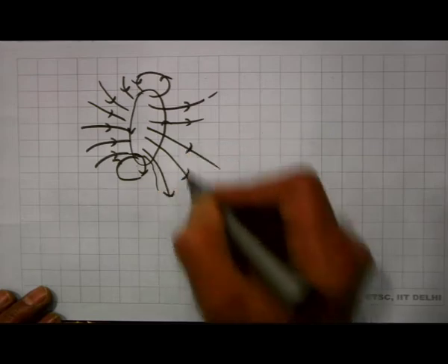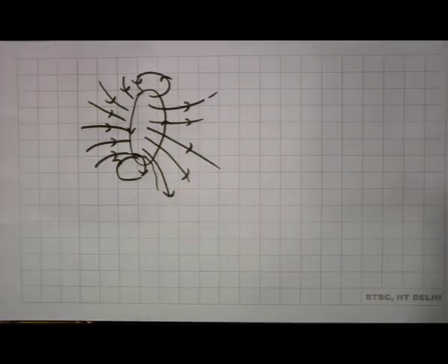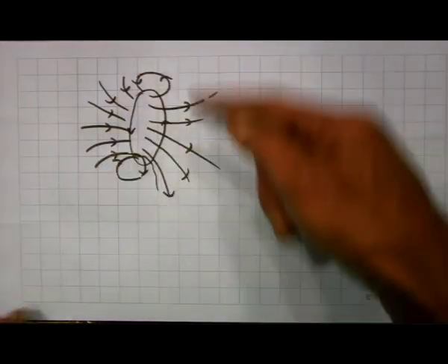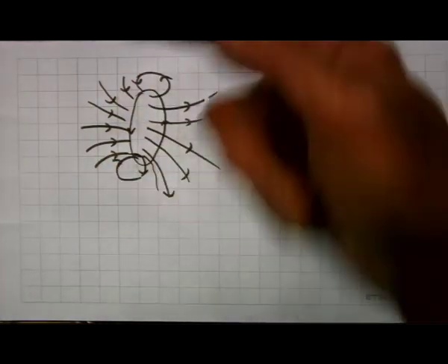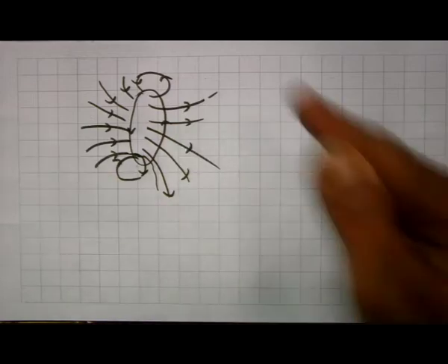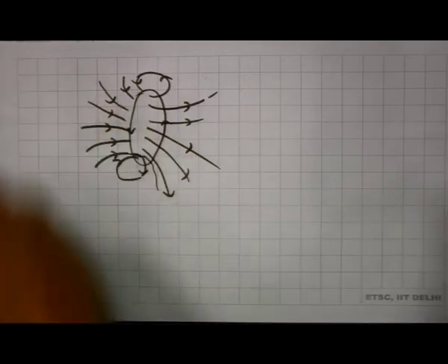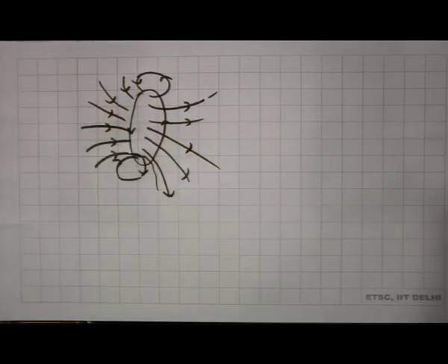Also notice that we have to use the right handed screw rule to find out the direction of the magnetic field. So, the current carrying conductor is carrying a current like this. As we have seen last time, if the current is flowing like this, then the right handed screw will move towards me, and so the magnetic field direction is towards me. So, a current going like this will generate a magnetic field like this, a current going like this will generate a magnetic field in the opposite direction.